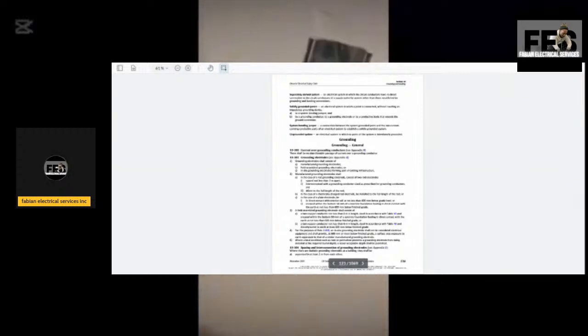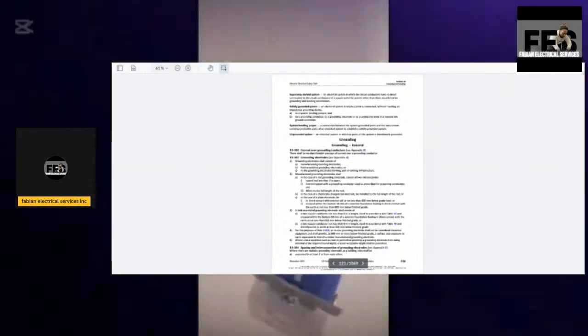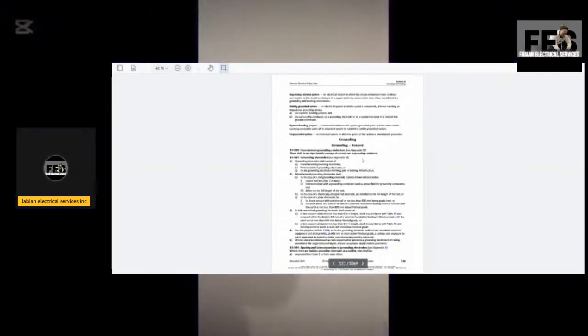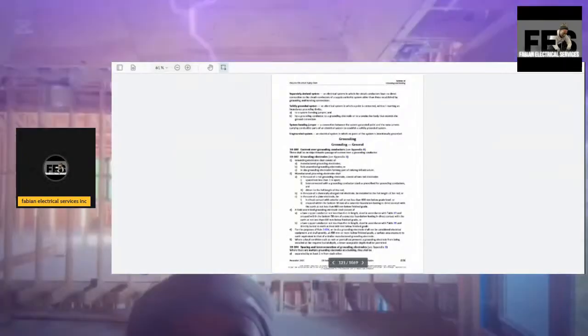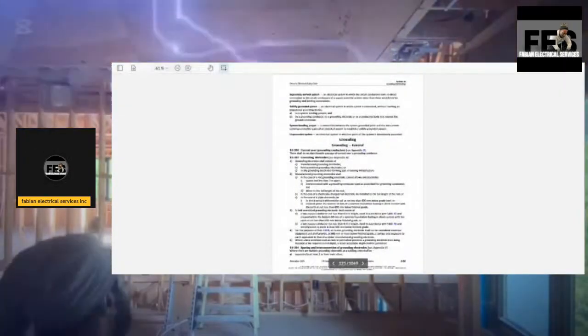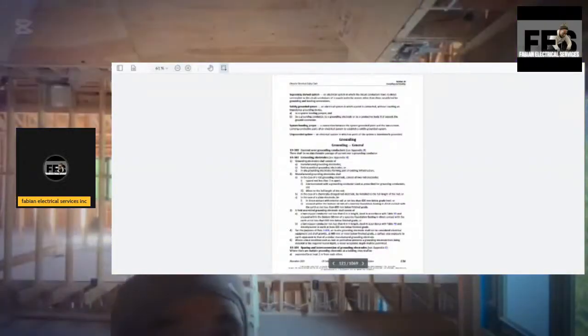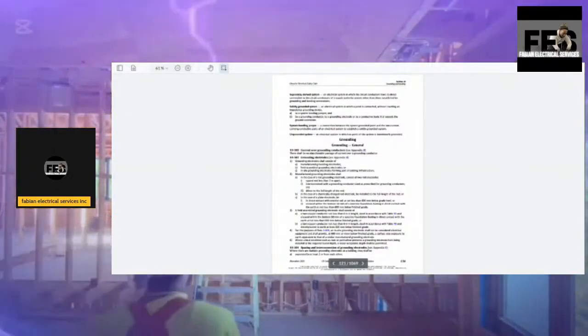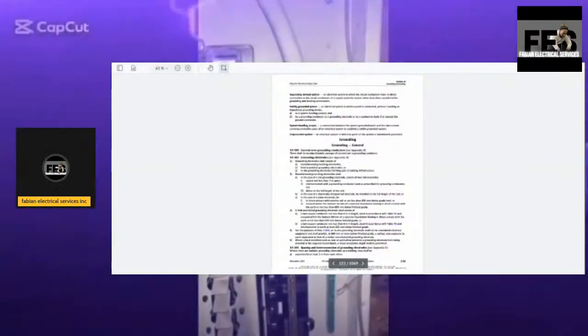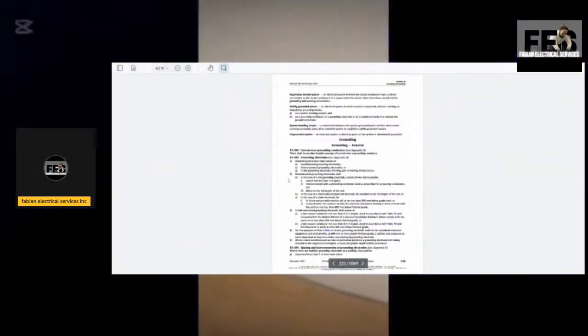Current over grounding conductors: there shall be no objectionable passage of current over a grounding conductor. Grounding electrodes shall consist of manufactured grounding electrodes, field assembled grounding electrodes, or in situ grounding electrodes forming part of existing infrastructure.